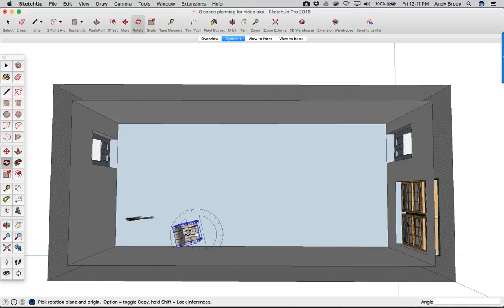And sometimes you know where you want it to start, you know where you want it to end, but you don't really know how many copies you want. To do that, to figure out how many you need, click your base point, your reference line, but then go to where you want the array to finish. See how I clicked at the end of my array? Now I can use the modifier. And again, if you watch down here, I'll type in slash and then 3.